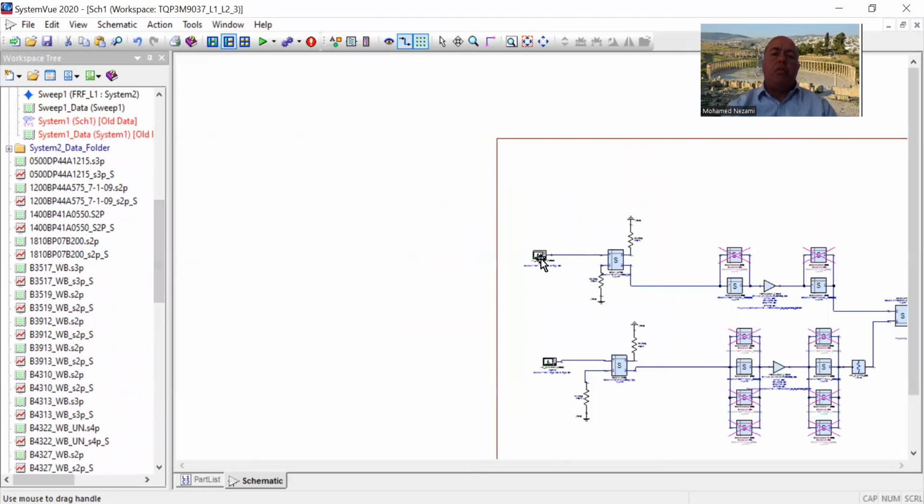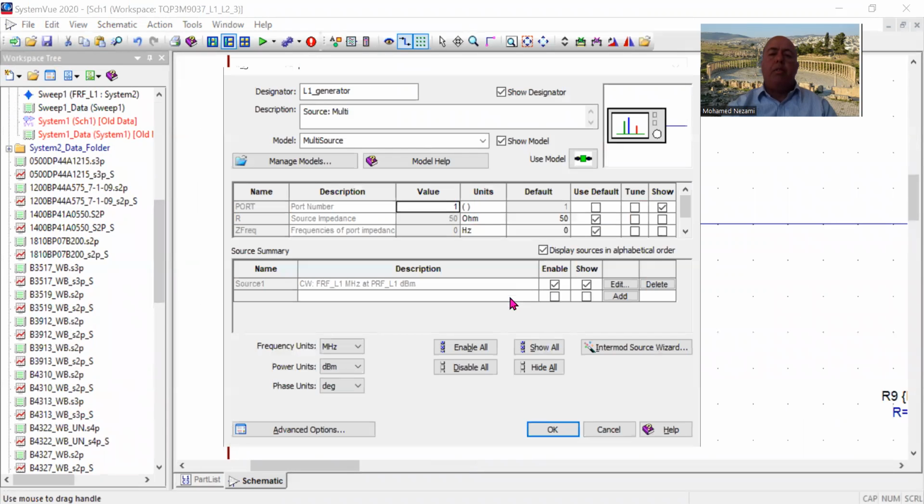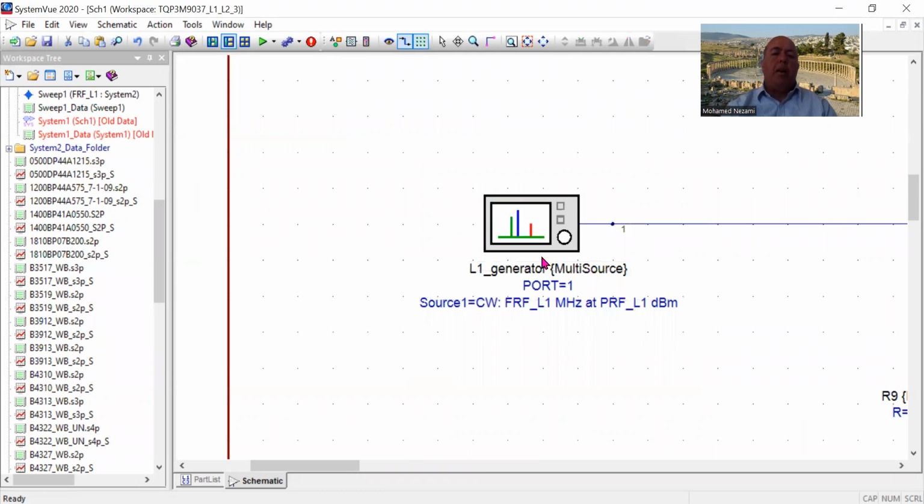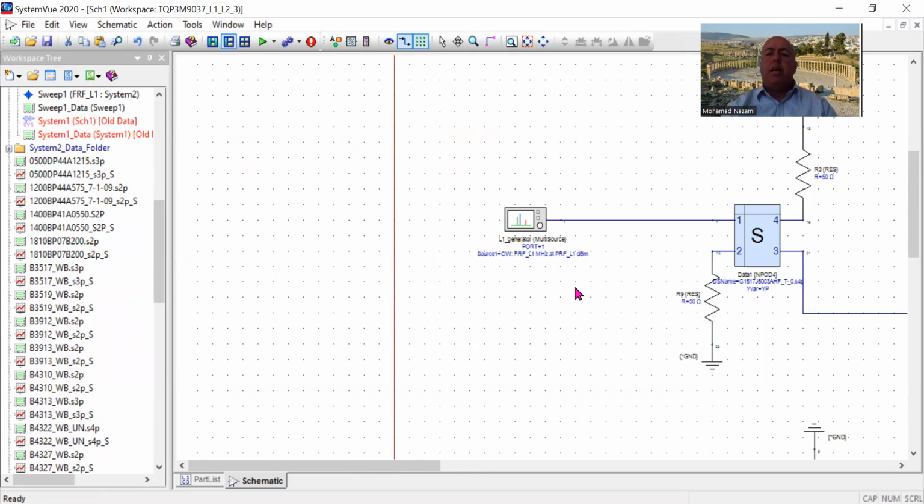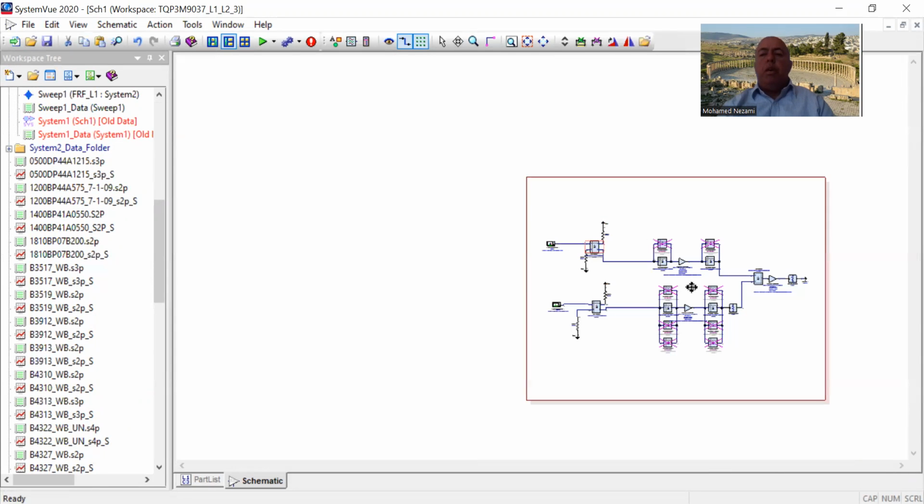We don't drive using 50 ohm. As you can see right now, we're driving this mimicking a 50 ohm device, but instead we don't need 50 ohm. We're going to make it point to an S parameter file, which has the antenna measurements, both on this side and on this side. So let's put some theory to this.